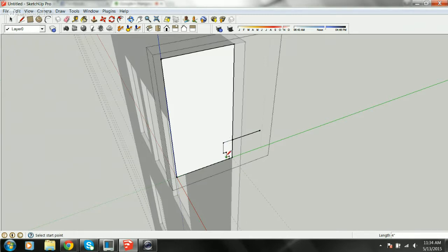Okay, and then I want this little slant to be, let's say we want to come back 2 steps. So I'm going to come up. I'm just going to draw a guideline in here. And see how it stays darker? Those lines are darker because it's not a closed object, whereas these lines have closed in a face. So I'm going to come up an inch off of that, and I'm going to come down here, select that. There's my angle.